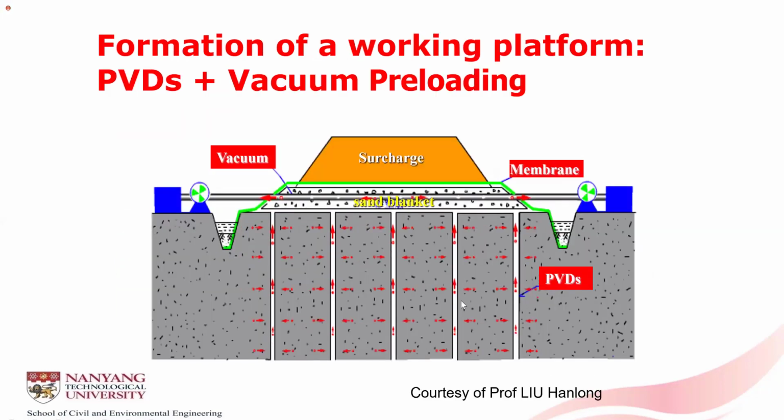When soft marine clay is used for land reclamation, because the ground is relatively soft, we will not be able to use a fill surcharge anymore, at least not entirely. So another way is probably using vacuum preloading as shown over here.